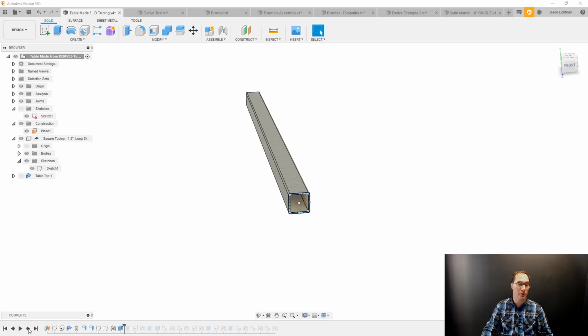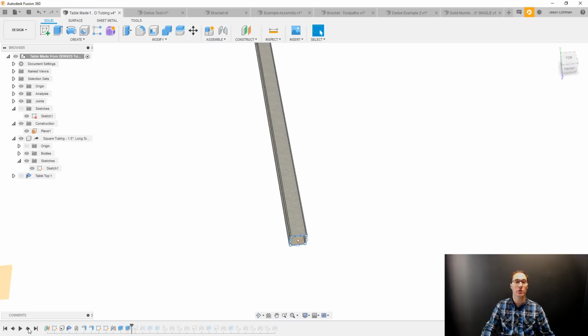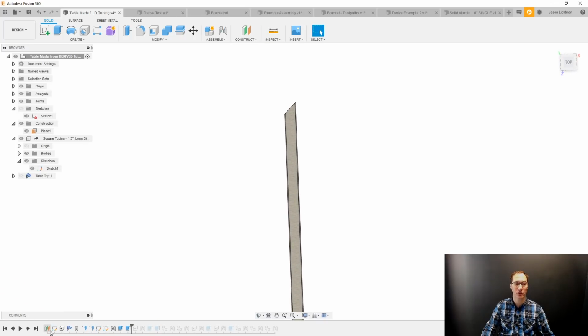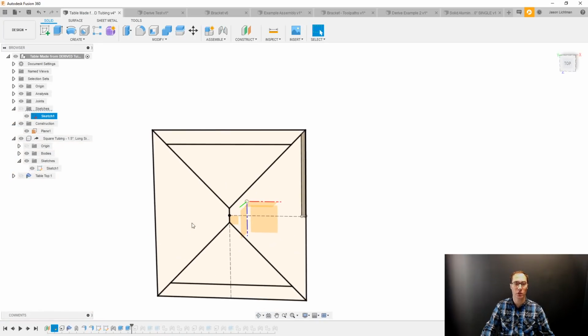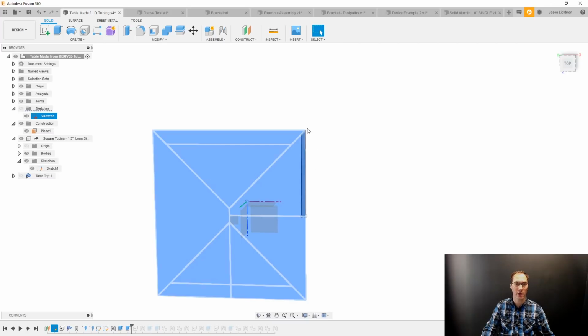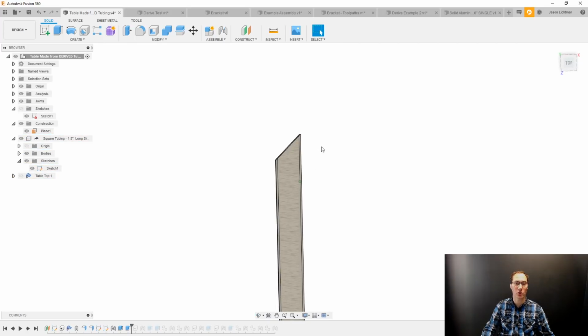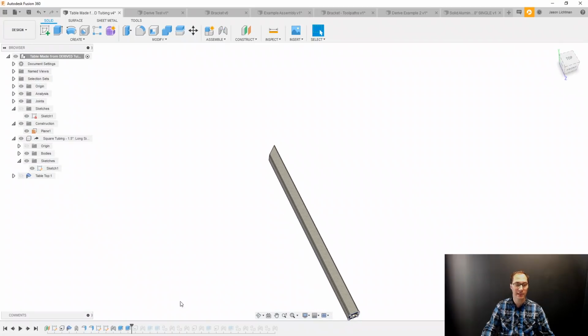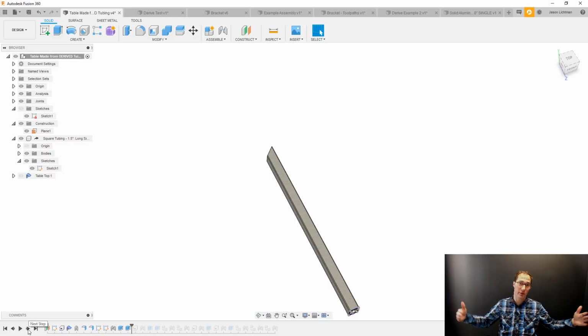And now we could extrude that in one direction. I also, remember I told you earlier, I had extra geometry in my top level sketch. These lines that I put are so that I could trim or miter these corners nice and perfect. So I did that right there. And now I want to make another tube. But here's the thing, my table is not a perfect square. My table is rectangular, it's longer than it is wide. So now I need another tube that is going to be the same diameter, but is not necessarily going to be the same length tube.